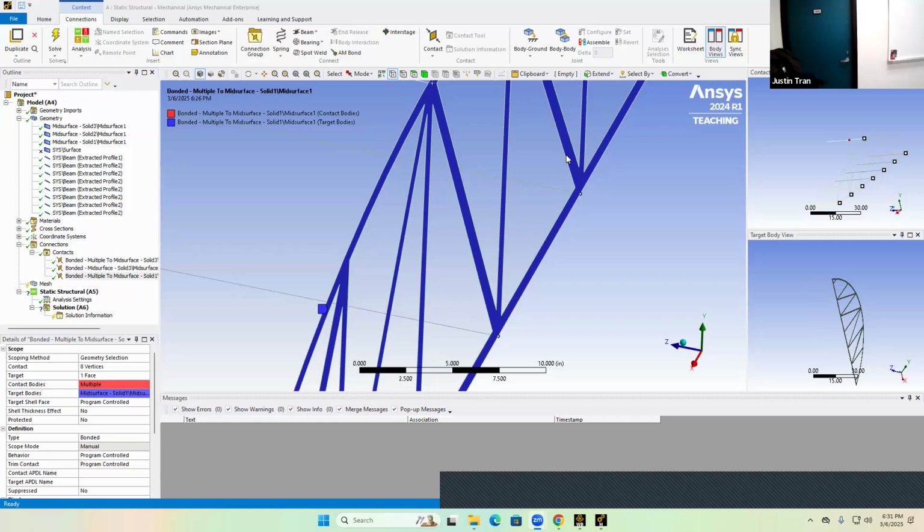So I tried to put the post on the side, but even if I put it on the inside, it's like that. Is that normal? Yeah, because your fixed supports, I'm guessing, are near the bottom. So the bottom is going to be much more stable, that's where the fixed supports are, but there's nothing really fixing the top. So if you apply a wind force, it's going to deflect. So yeah, this looks pretty good.